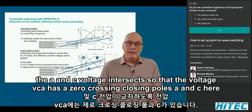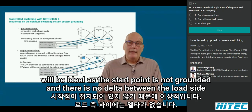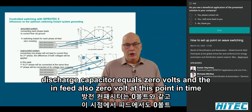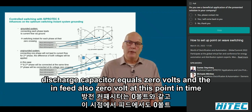Closing poles A and C here will be ideal as the star point is not grounded and there is no delta between the load side. Discharged capacitor equals 0 volts and the in-feed also 0 volts at this point in time.